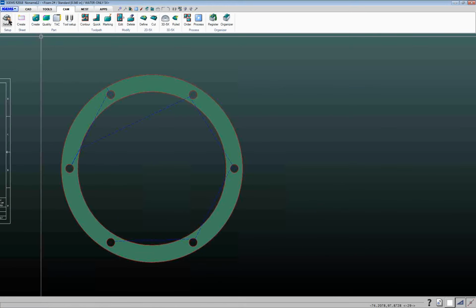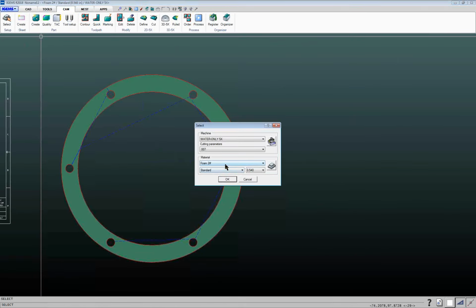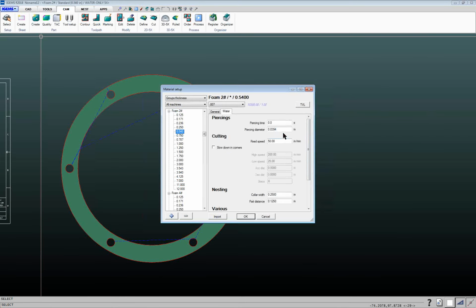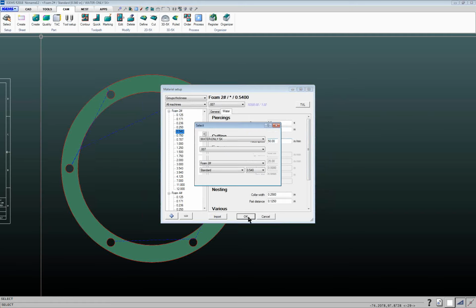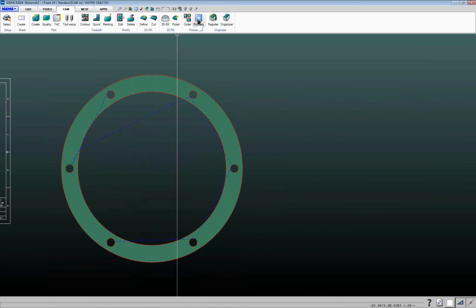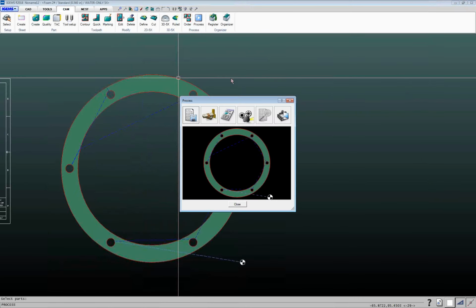If it's water only, it's usually going to be a fixed speed thing. So if we go into water only, we're usually using, let me group by thicknesses here, we're usually using the fixed speed option here. So regardless of whether I do the different qualities here as a water only part, it's going to end up doing this all at 50 inches a minute.